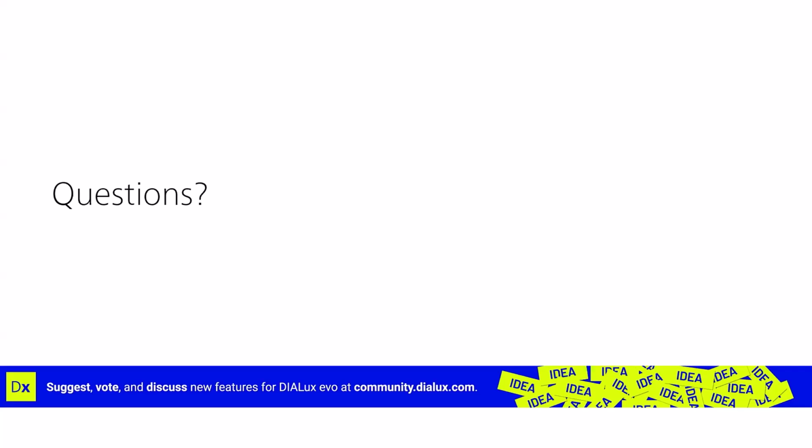Okay, thank you, Daniel. And some questions were about the creation of IFC files. If it's possible to use DIALux directly as a CAD software to create the complete building and to export the complete building as an IFC file. And there we must admit that's not the idea of DIALux. DIALux is a lighting calculation software, and you can import an IFC geometry, insert your luminaires, and export the luminaires as an IFC file.